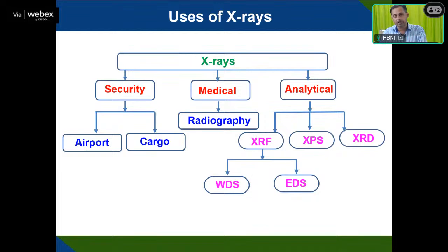That quantification is possible by using a standard. But for XRF analysis, you always need a very good standard. If there is no good standard, your result will have a lot of ambiguity. So we will discuss X-ray fluorescence spectroscopy, and how the X-rays produced are differentiated wavelength-wise, or energy-wise in energy dispersive spectroscopy.